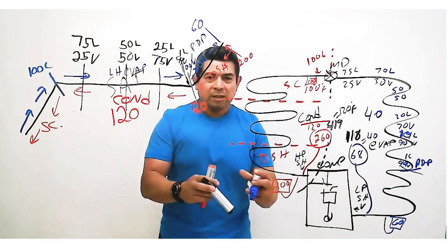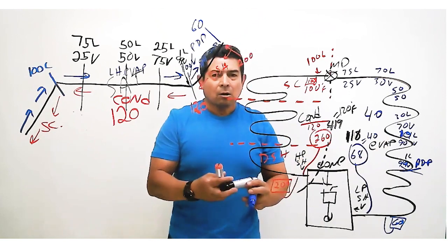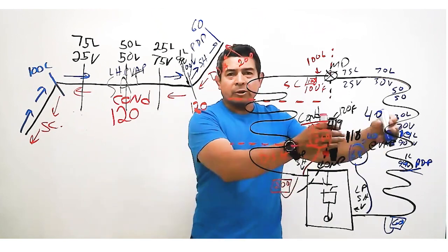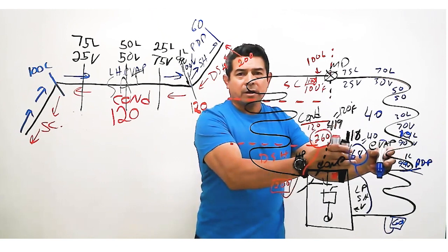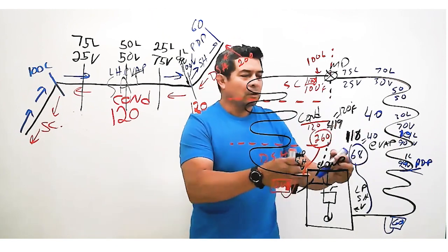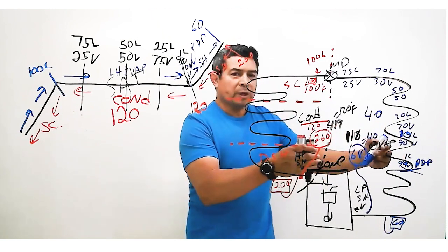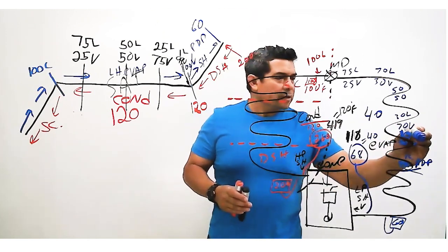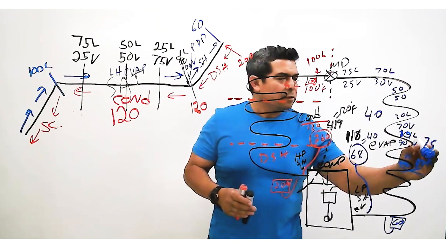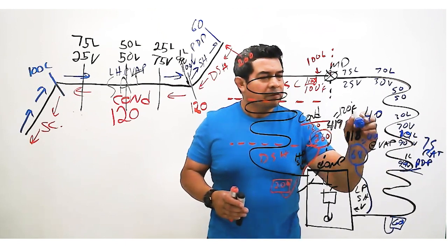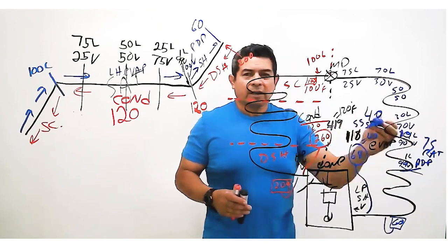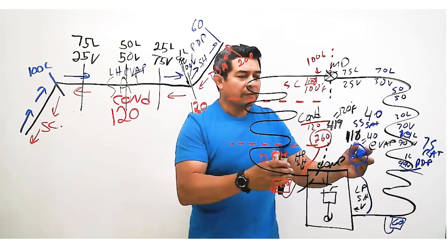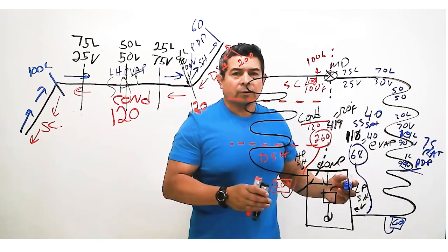Once the compressor compresses it, it takes all of this gas, all of this heat that we absorbed in the evaporator from the return air temperature, because we have 75 coming in, 55 going out. So we have 75 return air temperature, 55 supply air temperature. We absorb all of that heat and send it to the refrigerant.